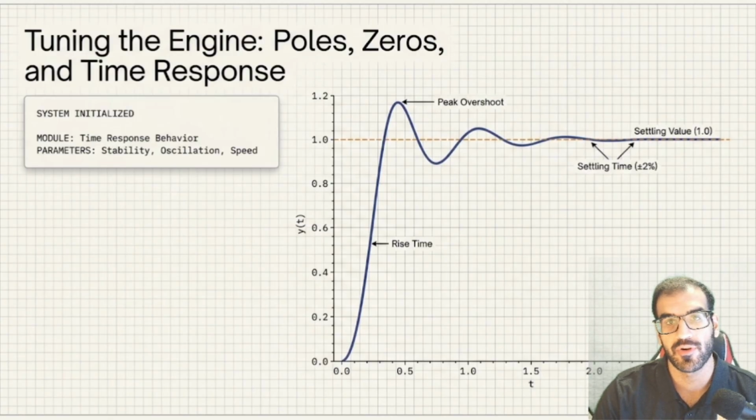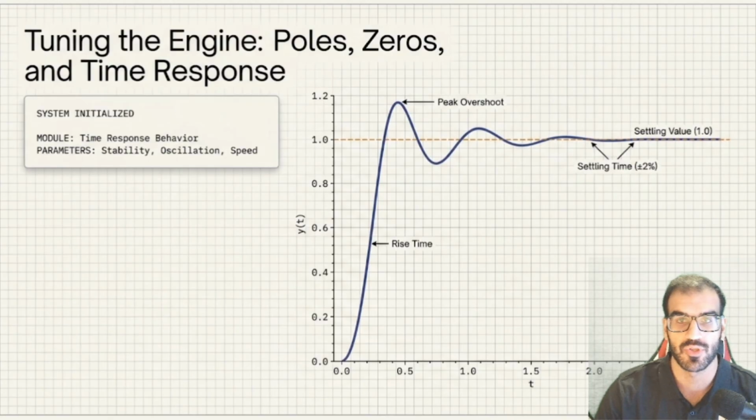As you guys remember, in the previous chapter we were talking about the zeros and poles and how each of them has an impact on our system itself. As we all know, poles are the DNA of the system, and they have the real impact on the steady state. This means our system is going to be stable or not based on the location of those poles. Zeros have a little bit of impact over the transient response.